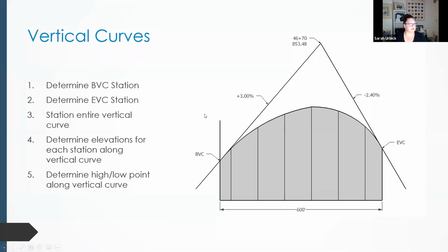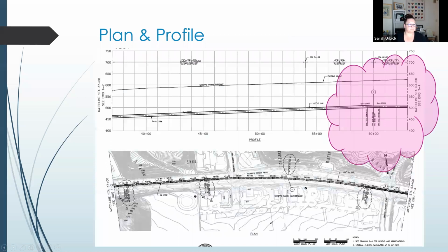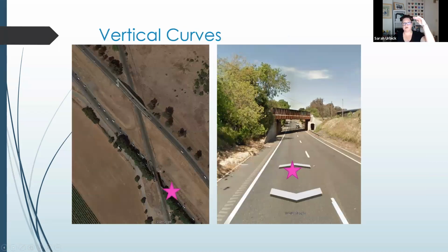Reasons we would want to find the low point and the elevation at the low point. Something kind of interesting. See this elevation here, the bottom of this ancient train track? The distance between any kind of overpass and the road surface underneath, in order to move heavy equipment, cargo, transports, that sort of thing, there has to be a minimum clearance of 13 feet 6 inches.